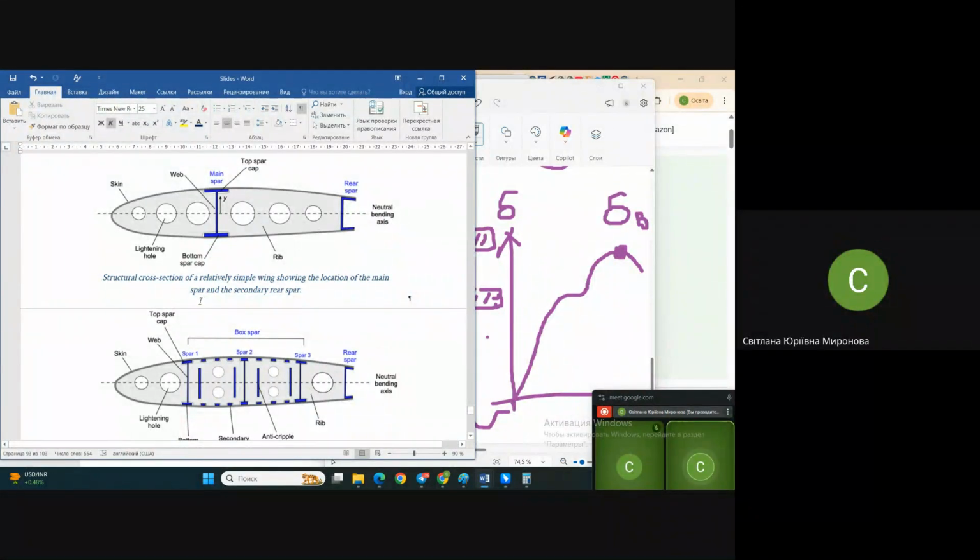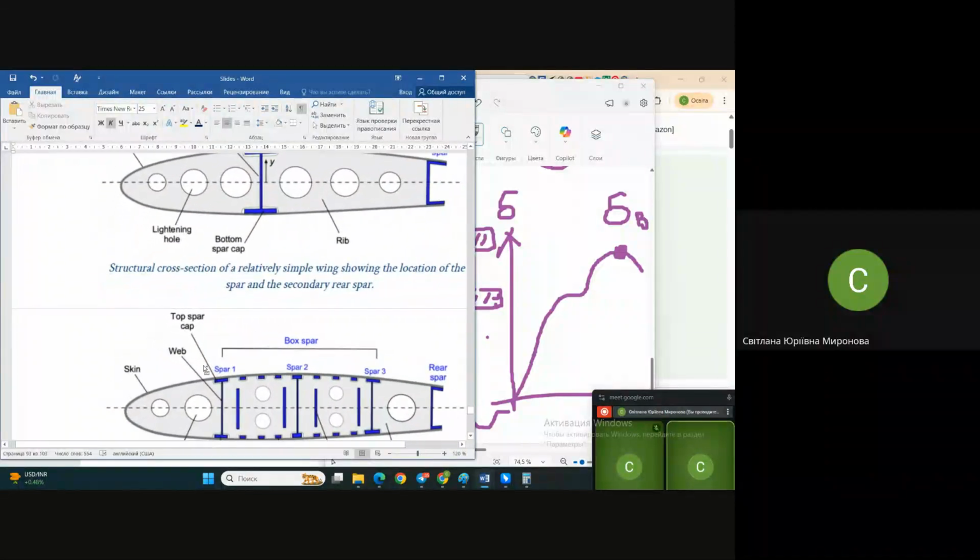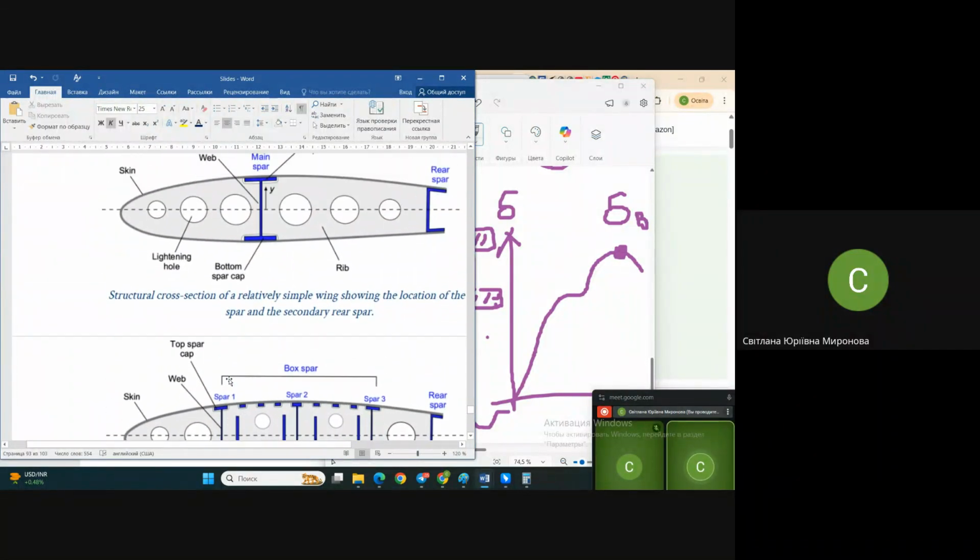And what do we see in the bottom picture? We have some spars, but they are not so massive. They are much more delicate, and by their size they are already barely distinguishable from stringers. Stringers have appeared, and stringers take part in counteracting the outer loads together with the skin and supporting skin. That is the so-called torsion box structure.